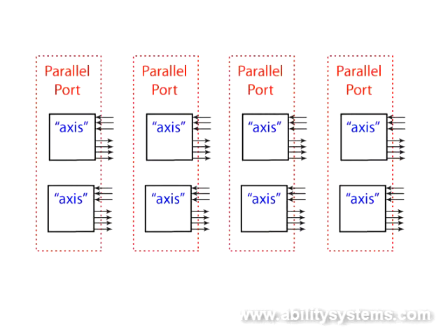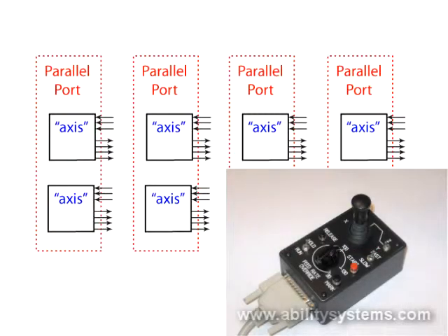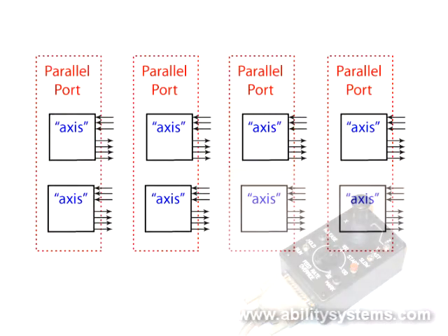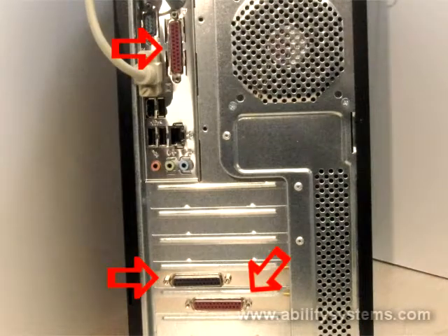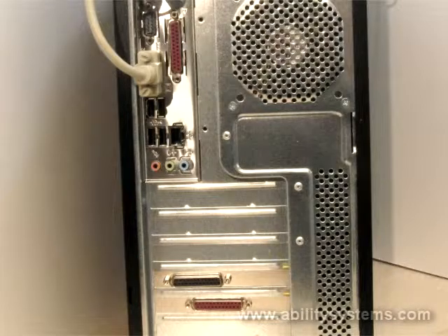Indexer LPT supports hardware installations of up to 4 parallel ports, thus comprising 8 of these symmetrical sets of signals. However, one parallel port is typically dedicated to a control module, similar to the one shown in Part 5 of this series. The remaining ports, therefore, support up to 6 of these signal sets. The most common installation consists of 3 ports, where the onboard port is used for a control module, and a dual-port parallel interface card provides 2 ports, thus 4 sets of signals.